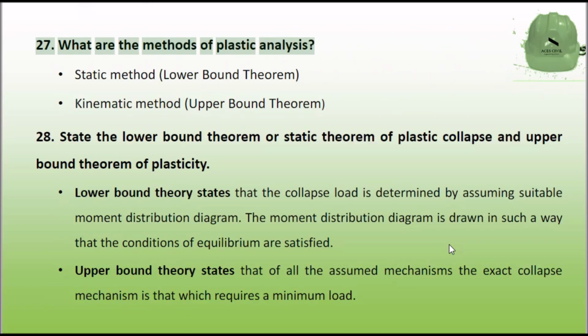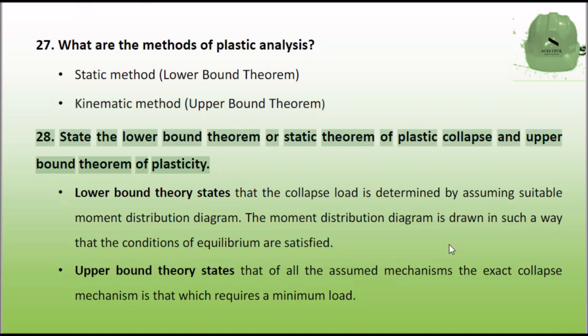What are the methods of plastic analysis? Static method, lower bound theorem. Kinematic method, upper bound theorem. State the lower bound theorem or static theorem of plastic collapse and upper bound theorem of plasticity.